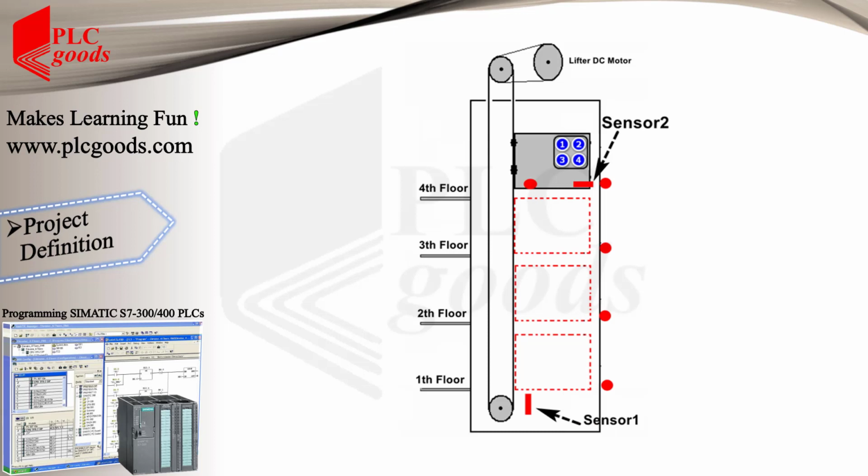After that, the elevator system can be used, and if any push button is pressed, the cabin will go to the selected floor. Wait 5 seconds, and then if there is another request, the cabin will go to another floor. Note that to update the cabin's position, the second sensor can be used. It produces a pulse when passing each floor.